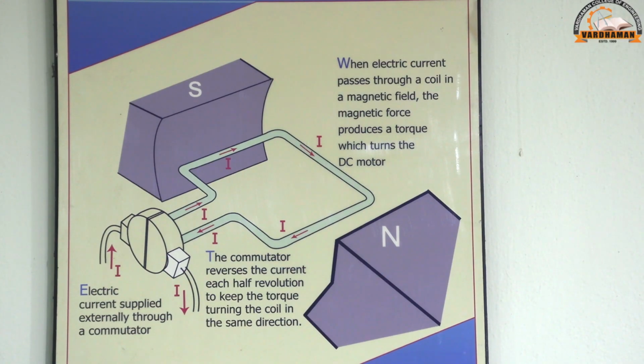So by controlling the excitation current which is given to the magnetic field coil, since it is an electromagnetic field coil, by controlling that current, you can increase the amount of flux and also you can decrease the amount of flux. By increasing or decreasing the flux, speed varies. The speed variation is possible in electromagnetic type of motors, whereas in a permanent magnet there is a constant speed. Neither can we decrease the flux nor increase the flux.